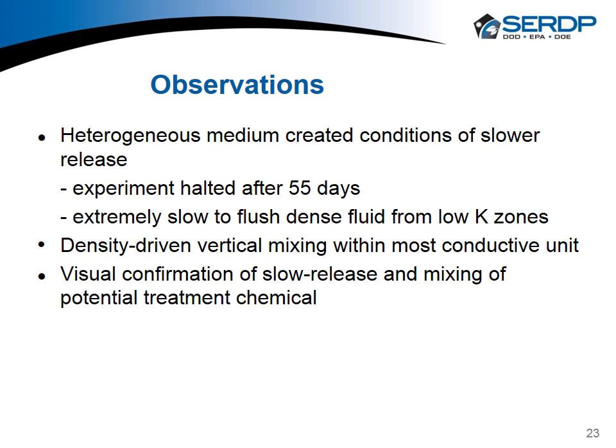Slide 23 is a summary of the observations of this experiment. And I think it's clear that the hydrogeologic conditions of hydraulic conductivity that we set up here did create conditions for slower release, and that's what we were trying to do. We halted the experiment after 55 days. We had backflow and so on. But it was extremely difficult to flush things from low K zones.